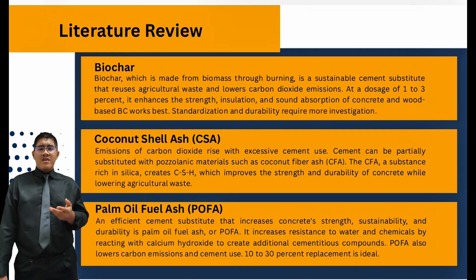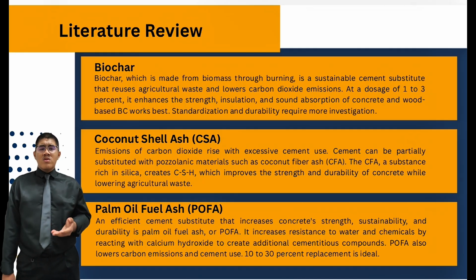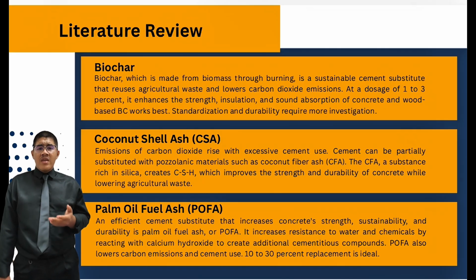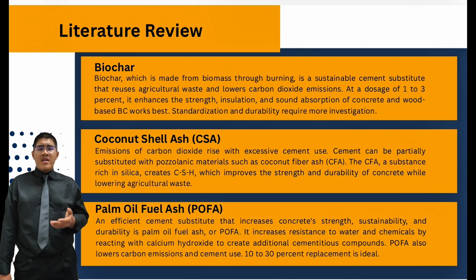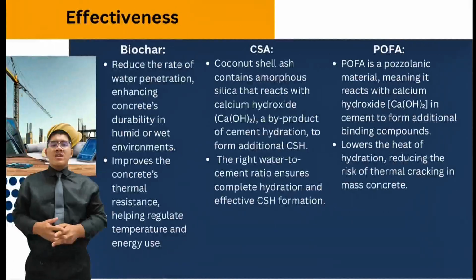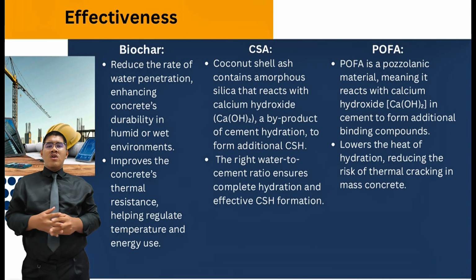Lastly, palm oil fuel ash, POFA. POFA is an effective cement substitute that enhances the strength, durability, and chemical resistance of concrete. It reacts with calcium hydroxide to form additional cementitious compound and helps lower carbon emission. The ideal replacement level is between 10 to 30%. Now let's move on to the effectiveness of the material.